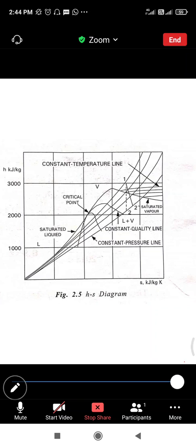We learned the very important dryness fraction, x equals ms by mw plus ms, a ratio of mass of dry steam to the mass of wet steam, and the degree of superheat. Also the properties of wet steam, the external work of evaporation, and internal latent heat.